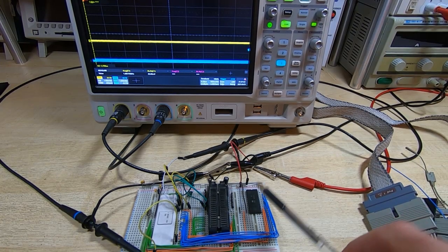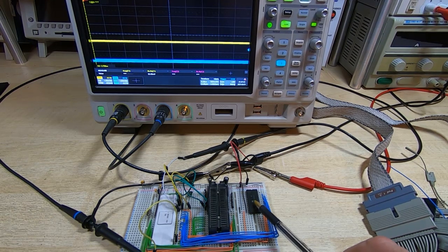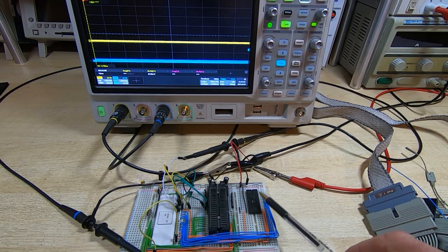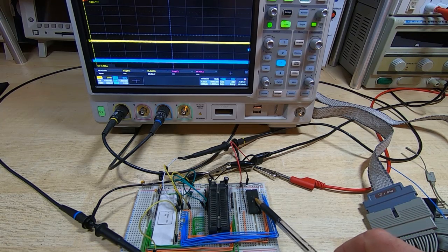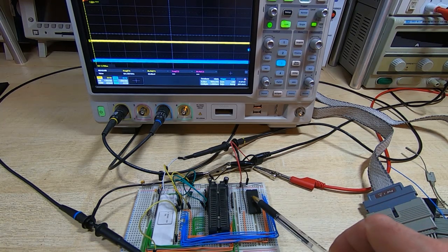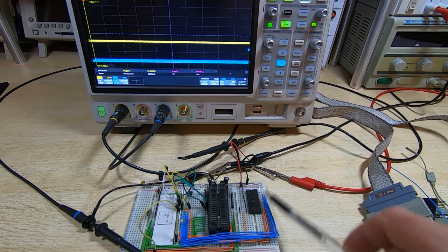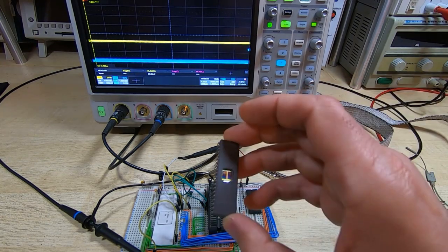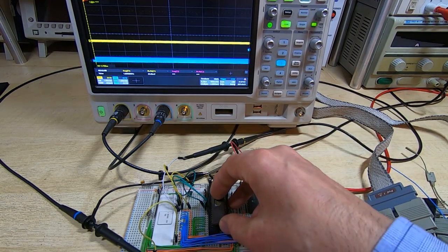So as you can see, I've got one of the port chips installed. Although we only need to toggle one bit, I have to connect up the entire 8-bit data value because, as I said, that is also the address bus in the first phase of sending a value or retrieving a value from the port chip. Again, don't know if this chip works yet, but I've got it hooked up what I think is correct, and what we can do now is insert our new program.